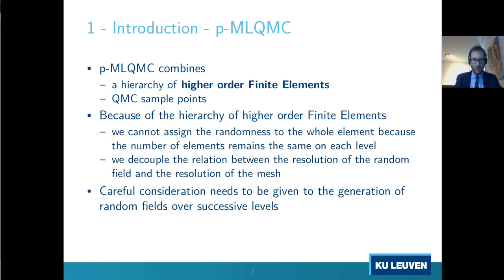So what we need to do is decouple the relation between the resolution of the random field and the resolution of the mesh, because we're not refining the mesh in an H way, but we still want a refinement of the resolution of the random field. We will need to decouple those two, and this will be a major point of talk in this presentation. So we will need to give careful consideration of the generation of the random field over successive levels, in which points we generate discrete values, and how to incorporate them into the model.